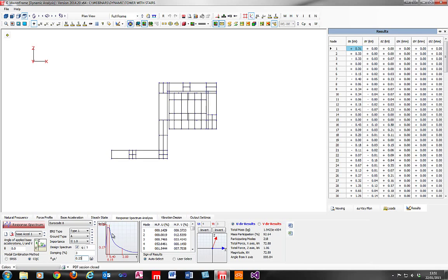And we actually draw the little response spectrum graph here, whereby this response spectrum basically gives us the peak acceleration which occurs at these various different periods, which is essentially another way of representing a natural frequency. So we're essentially looking at accelerations, combining them and converting them into forces. That is what's going on here.